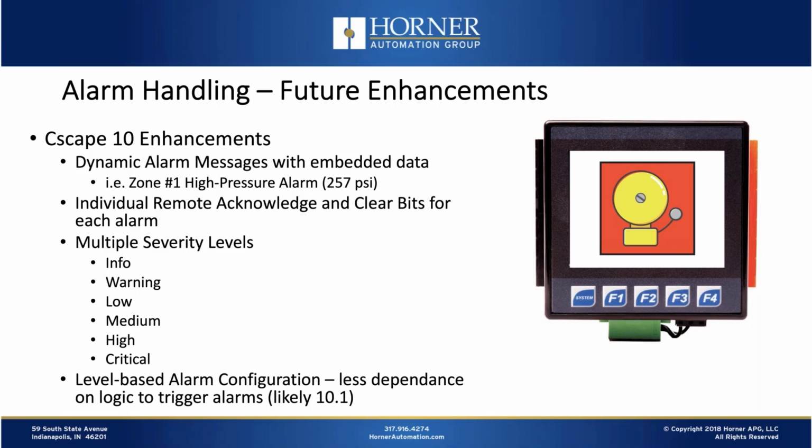Also, if you remember, for remotely acknowledging and clearing alarm conditions, say from a SCADA package or elsewhere, you really only currently have one set of bits for acknowledge and clear, whereas in the future, you'll have one bit per alarm. So that was definitely another highly requested feature.